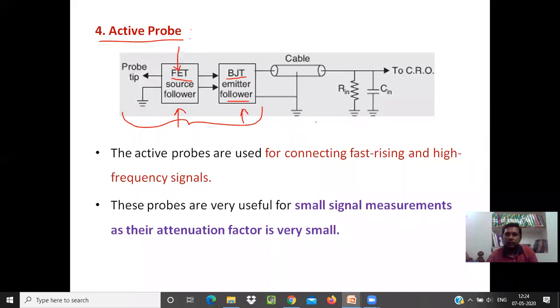Suppose I have a circuit here. Let's say this circuit has some resistor and a capacitor. Now I am using a measuring instrument for this, my voltmeter. I want to measure the voltage across this component. So the input terminals of this voltmeter are connected across the capacitor, so that we can measure the voltage across the capacitor.